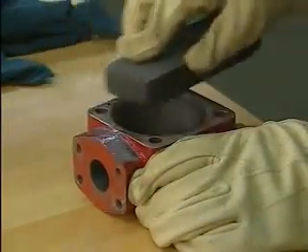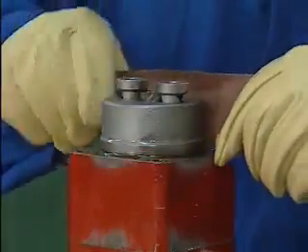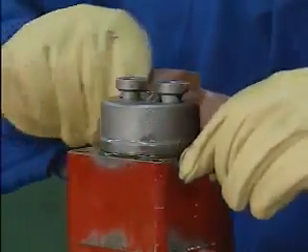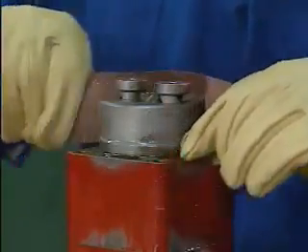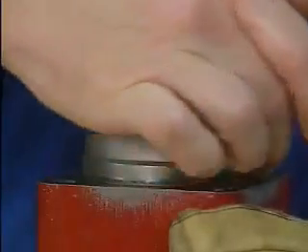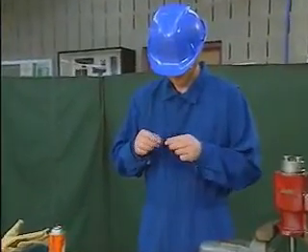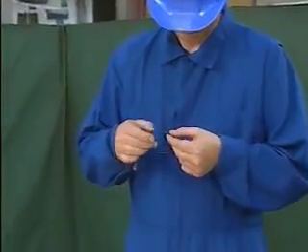Burrs and sharp edges on the flange face can be removed by stoning the surface. Imperfections on other parts of the flange, such as the sleeve, can also be removed by polishing the surfaces with grit paper. The sealing surfaces are in good condition, so the mechanic then checks the O-ring selected for this application to make sure that it's free of cuts or other damage.